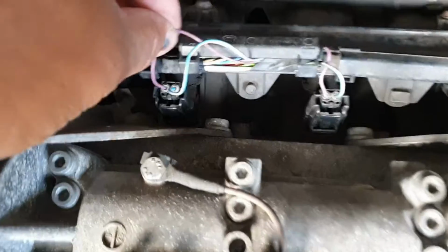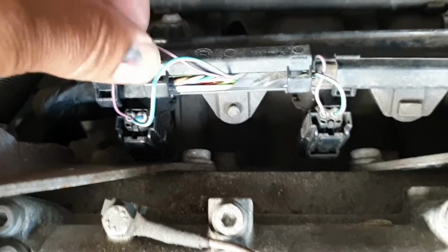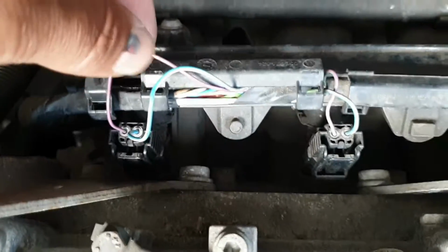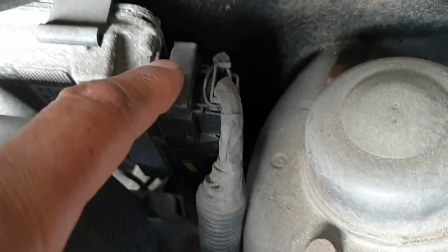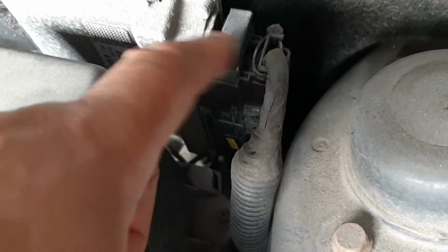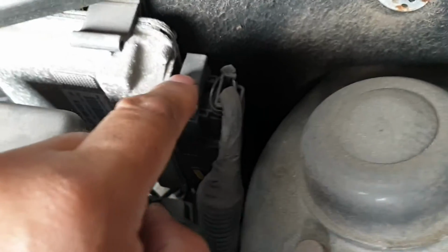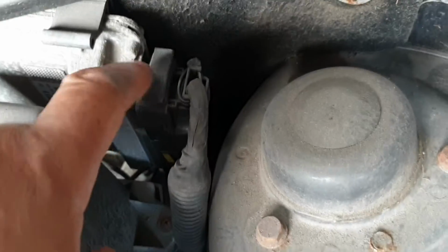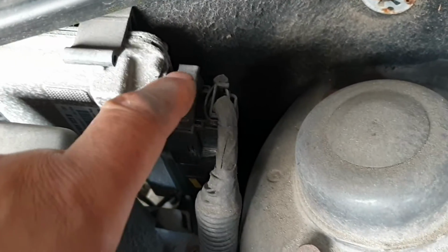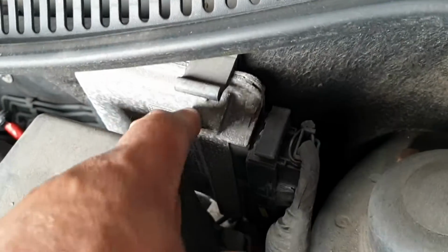Okay. Now I am going to back probe this wire at the ECU connector here. I'm going to point out the pin number and the connector number on the wiring diagram, and then I'm going to back probe this wire here. If we have source voltage here at the connector, that will prove that our wiring from the injector to the ECU is good. If we have zero voltage, it means that the wire is broken somewhere, or it has an open circuit or high resistance between the injector and the ECU connector. So we are going to prove what we will have.